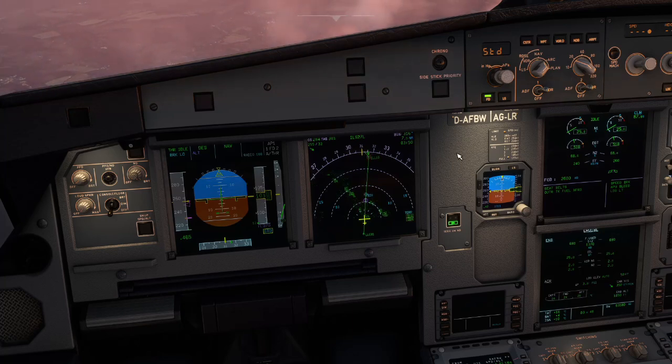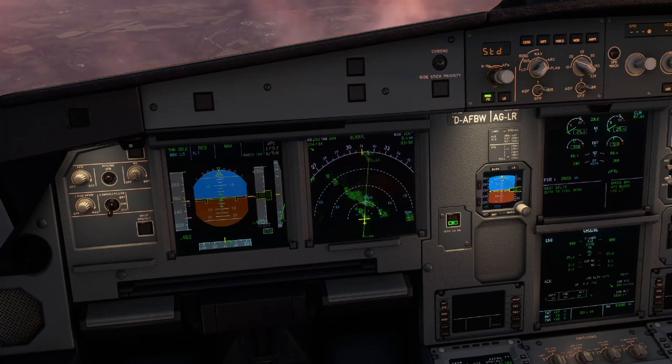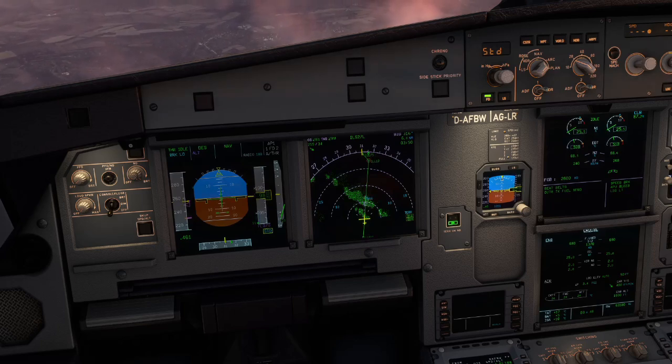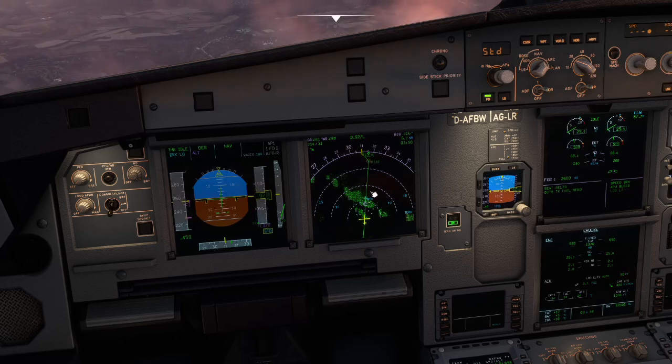Range again a little bit. It shouldn't like that 180 constraint. Don't be afraid to use the spoilers if you need to. They have absolutely done their job. But if I hadn't used them, we would have struggled with this profile. It's only just recapturing it.